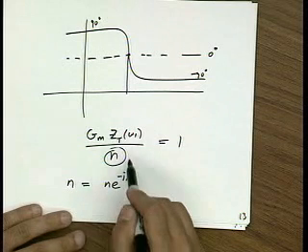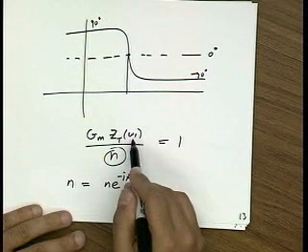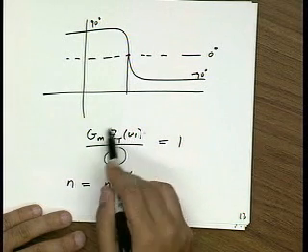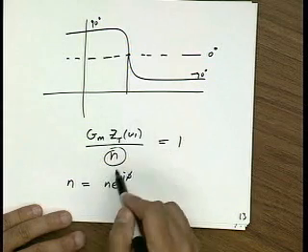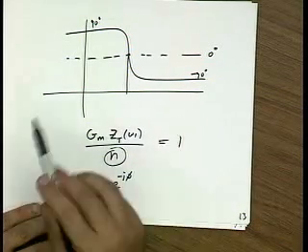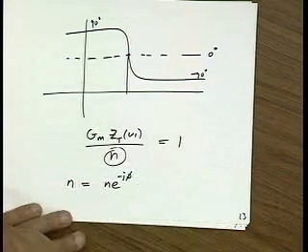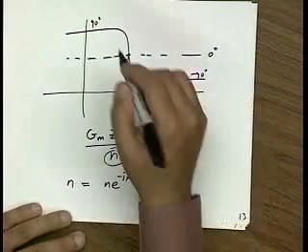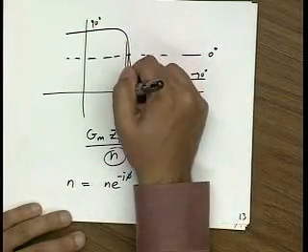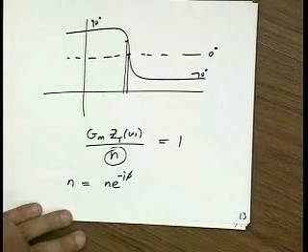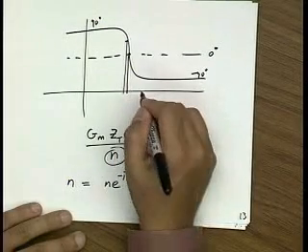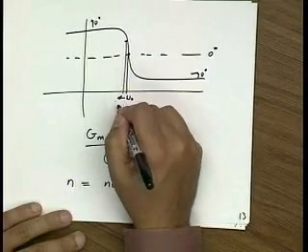Then that phase delay has to get compensated, because now this needs to become complex, so that overall the loop gain is 0 degrees exactly, right? That means I'm going to have a little bit of phase advance from the tank to compensate for that phase delay. So my frequency is going to shift away from omega naught.